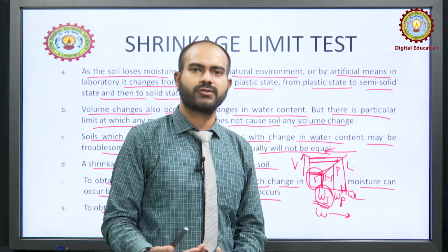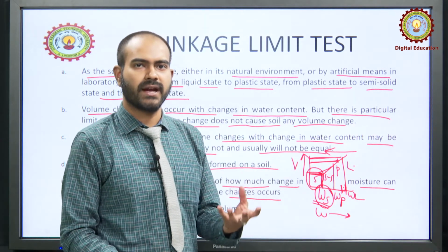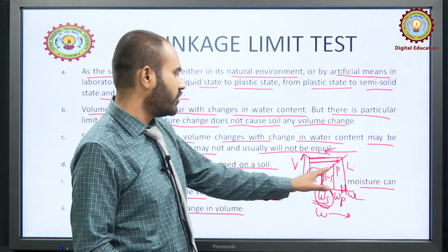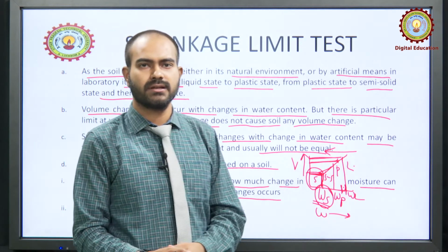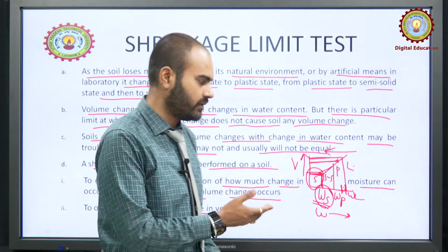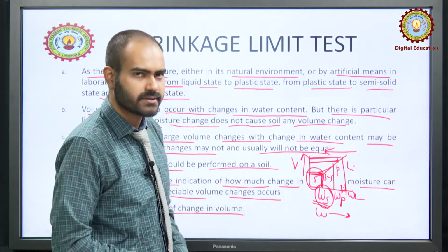So if there is swelling soil, swelling meaning to expand, okay, expansive soil. If there are expansive soils, their volume change will be very high with respect to a slight change in the water content. So we have to deal with those, okay. So we will be finding all these parameters first, okay.